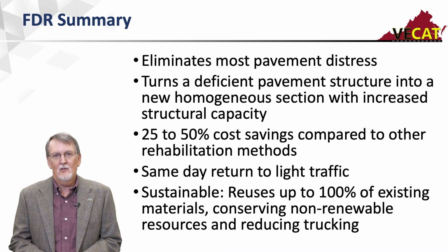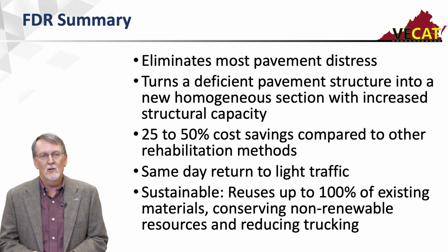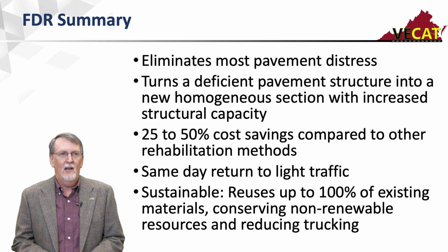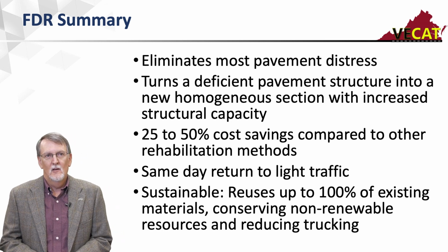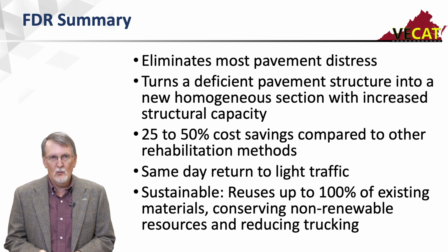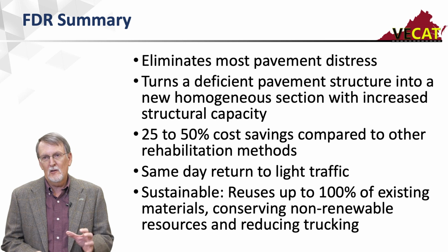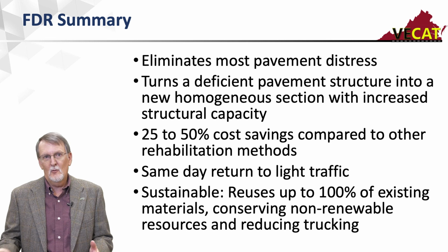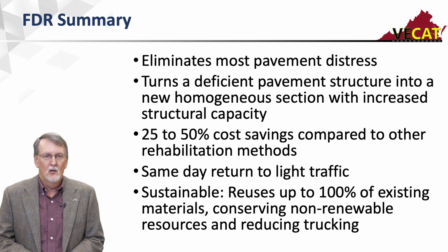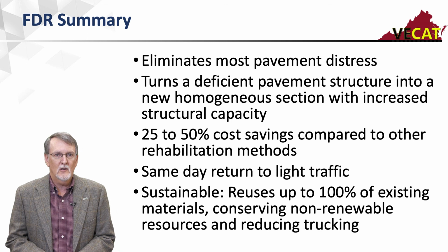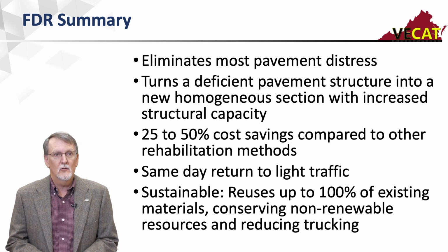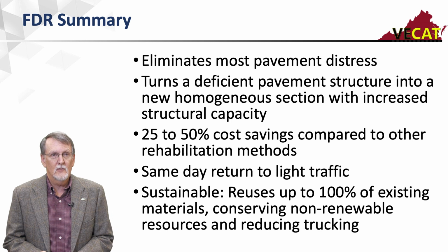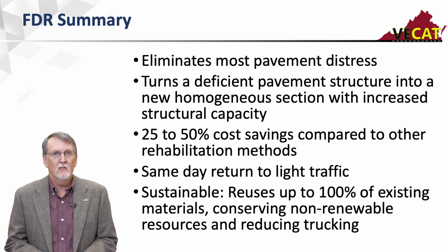If you think about it, I'm going to take that existing road. I already own all those materials. I'm going to grind it up, add a stabilizing agent, and recompact it. One of the other things that makes it quite sustainable is I'm reusing 100% of the existing materials. If I'm going to reconstruct it, I've got to haul all that material off, and then I've got to turn around and haul all new material in. So FDR greatly reduces trucking and conserves non-renewable resources. And I can return it to traffic the same day, light traffic. So very cost-effective, very sustainable, well-performing process.